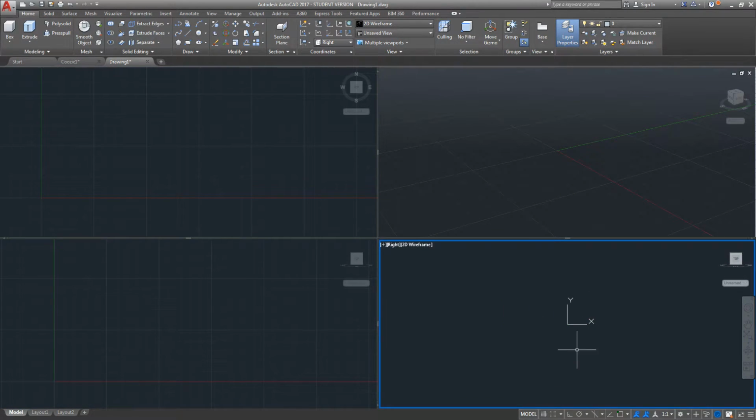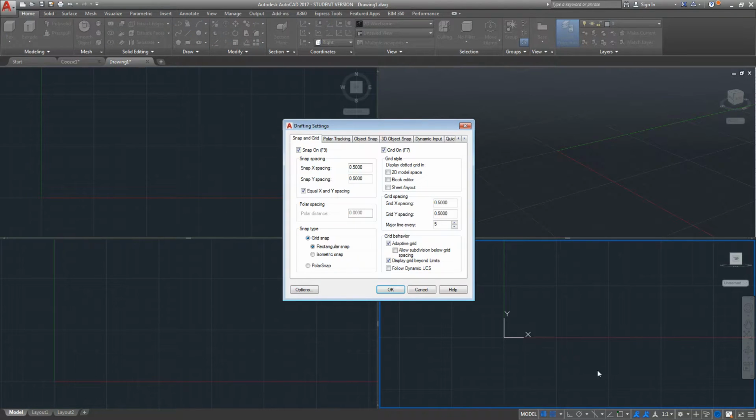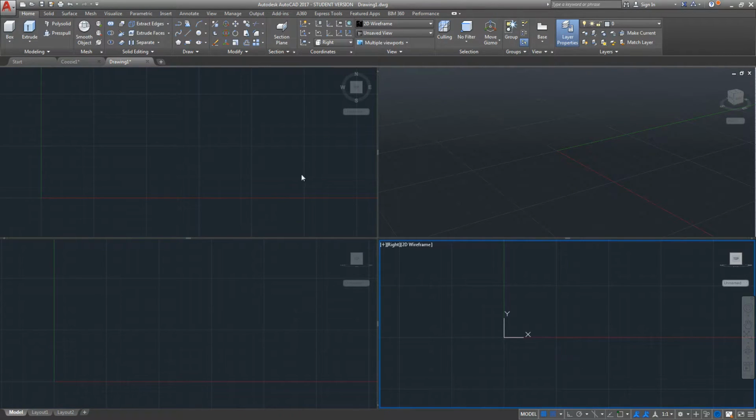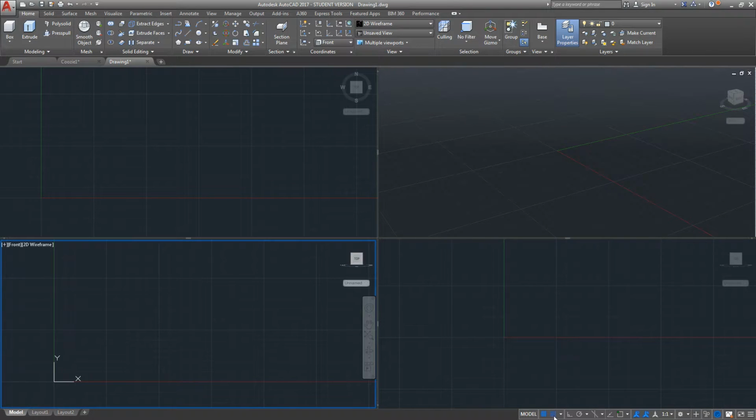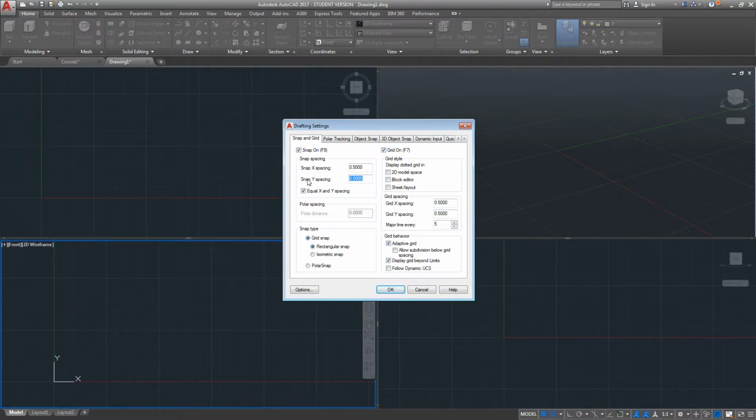Oh, there's no grid here. See that? There's a grid here, no grid. It's right here. Grid. Snap on. That snaps to the grid. I like to change this to 1/8 inch. So if you do that, click that on, click this arrow, snap settings. 0.125 on the bottom or the top. This little guy here will make sure that it automatically changes.